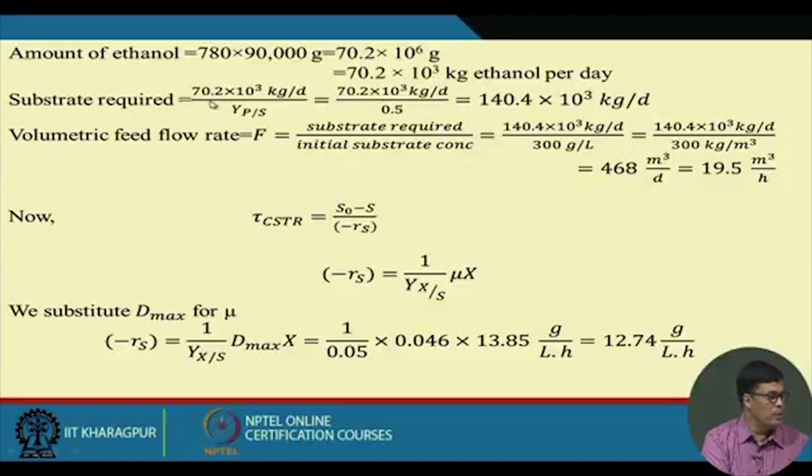Then we can easily find out how much substrate is required. This is 140, because of the YP by S ratio, that is gram ethanol per gram of sugar. So, you can easily calculate how much sugar is required per day. Then we can find out the volumetric flow rate, because this is the substrate required divided by the initial substrate concentration, and we can find out the flow rate.